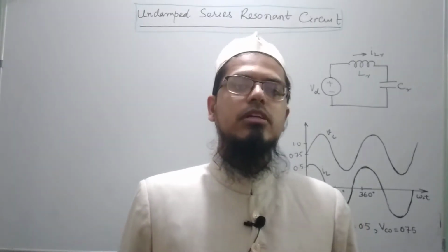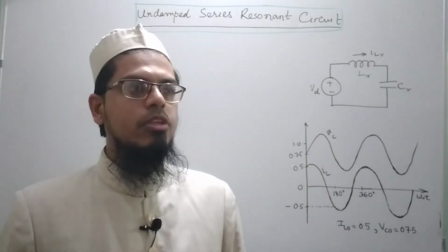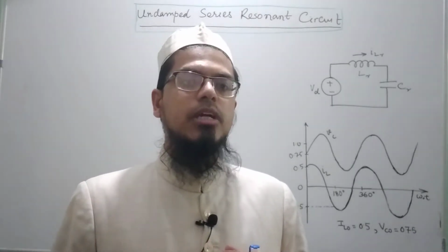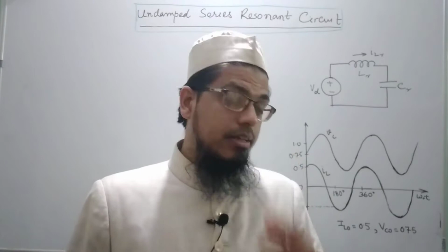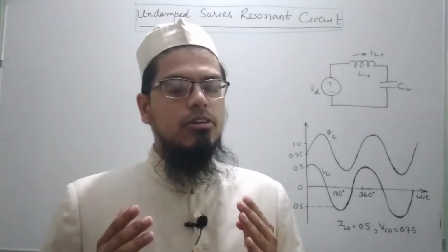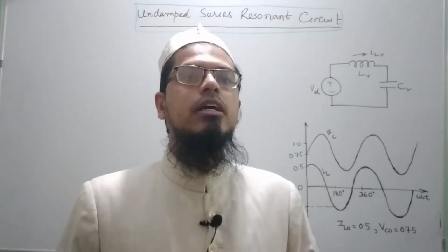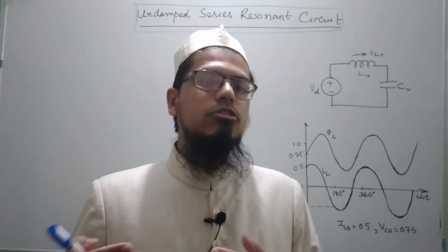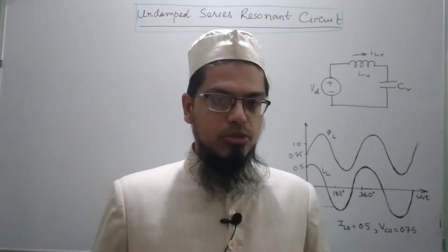In today's lecture we will be starting the basics about load resonant converters. Load resonant converters are basically those type of resonant converters which utilize some type of tank circuit with the load, thereby employing zero voltage and zero current switching.